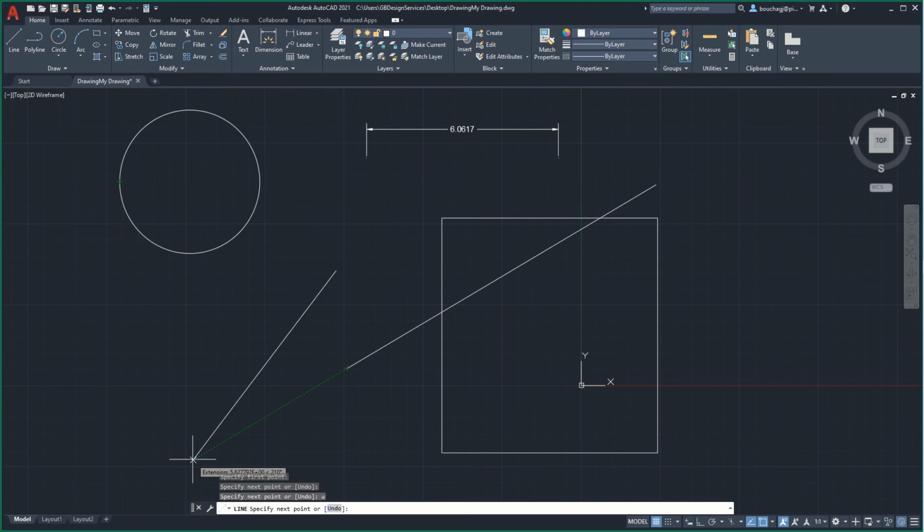One possible use for this extension tool would be to use in combination with the Object Snap tracking tool to allow us to locate where our line segment would intersect with a vertical line extending from the quadrant of this circle.